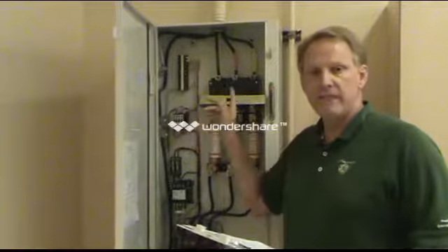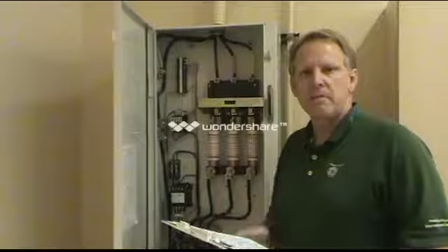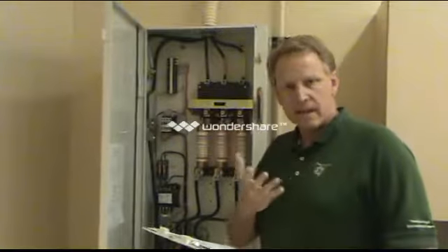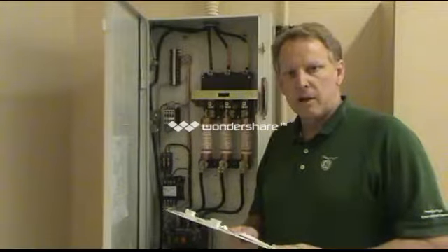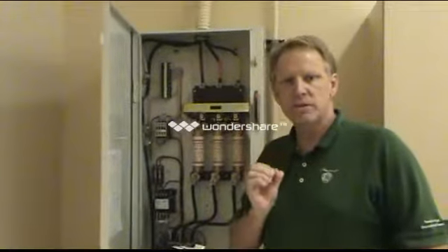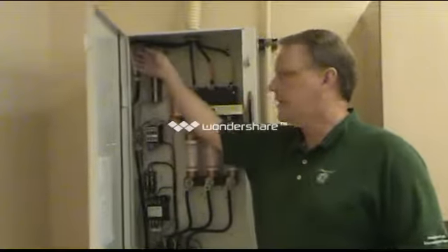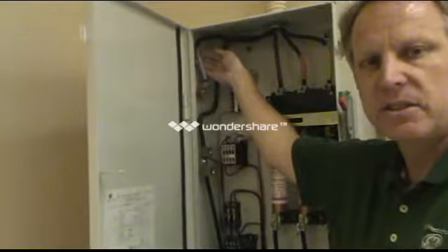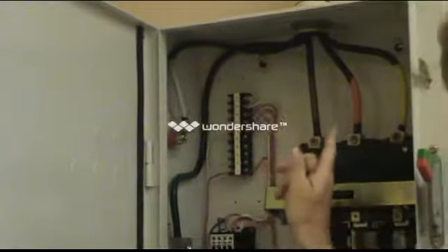Going from your ground to your phases on a 480 volt system, that should be about 277 volts from ground to each phase. Again, those should be balanced also. Is there a neutral wire present? Now, there's no system in GE that uses that neutral. So you may have a neutral coming in, I'm going to show you up here, and it's not connected, but I still want to have the voltages between neutral and each of those phases.